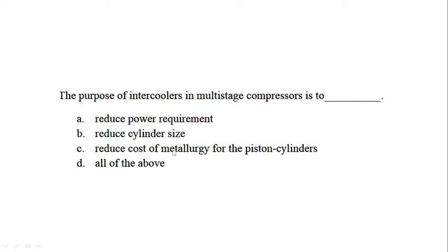So this one will be option C. Statement 1 is false. So this one will be the leg support. It will be used for vertical vessels, not for horizontal vessels. But the skirt support, this is the skirt support, will be used for vertical vessels.